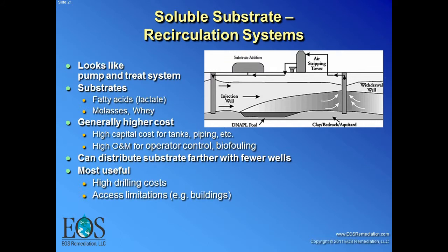If you're continuously injecting substrate into an injection well, the wells tend to clog up over time, so you've got to get somebody out to clean it up. But one of the big advantages is that you can spread it out. You can use somewhat fewer wells. Typically, I tend to see this kind of design is most useful where you have really high drilling costs or just simply access limitations. You can't get underneath a building or something.